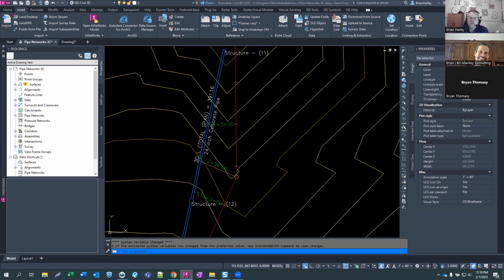If we were doing something like that, first off, we'd probably divide the 400 acres into phases and then divide those utilities based upon the utility type: sanitary sewer, storm, and water. Those would be on their own drawings per phase, and then we'd just deal with the hookups. 400 and some odd acres, that's a big project. I'm jealous.